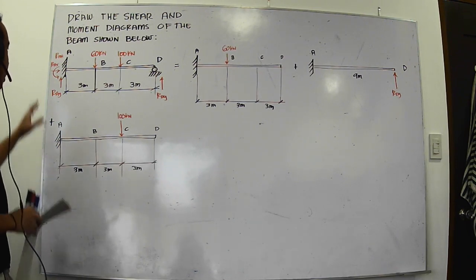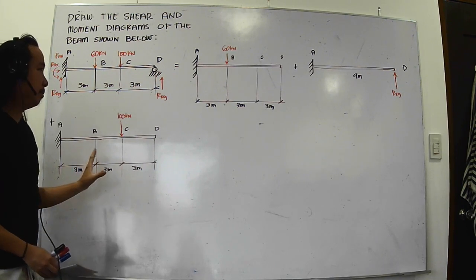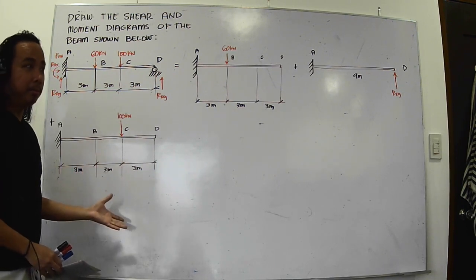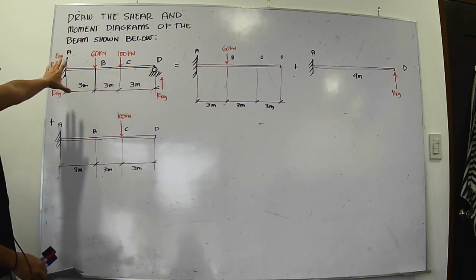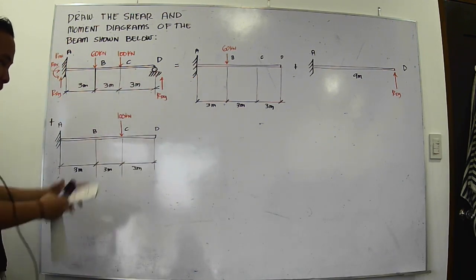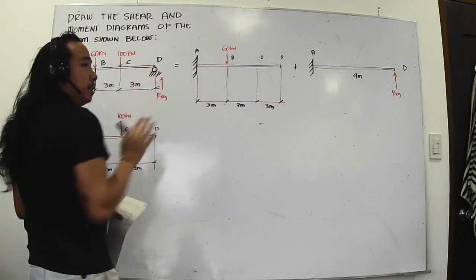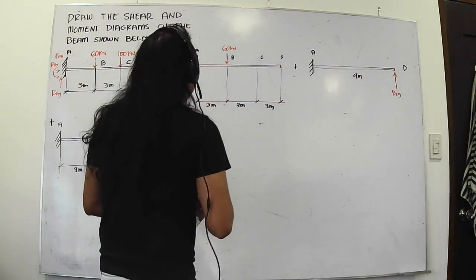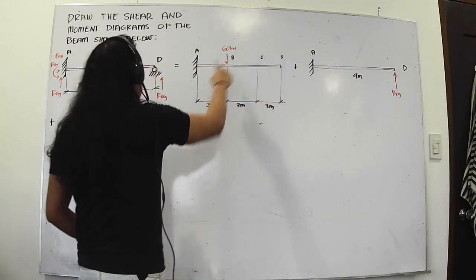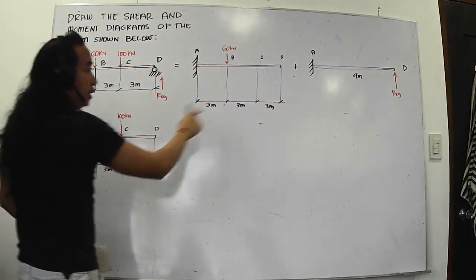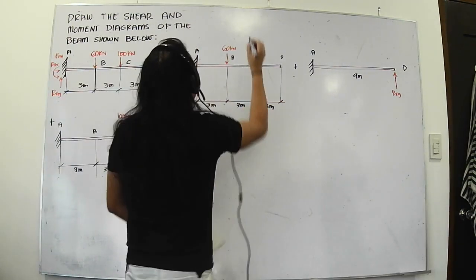Now, this is one complicated beam that I will break down. Basically, nothing is lost, because if you add all of these three beams you will have this. But with that in mind, we have consistent deformations. These are the applied loads, the beam with applied loads, and this is the beam with the redundant reaction. Redundant, okay?